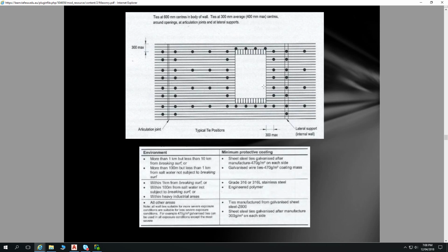But typically on a floor plan, that floor plan is very busy already. If we were specifying control joints in that, it would be a fair bit more. So our brick veneered walls have to have control joints built into them, because if we don't have a control joint in our wall, we have a really long run, there'll be a little bit of flex in the building and in the concrete slab, and that will just go straight through the brickwork. So that control joint enables some movement of the brickwork.